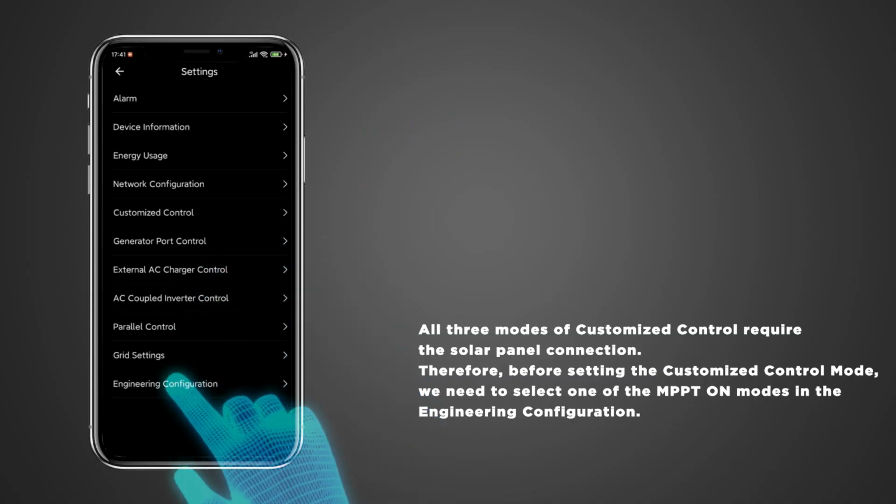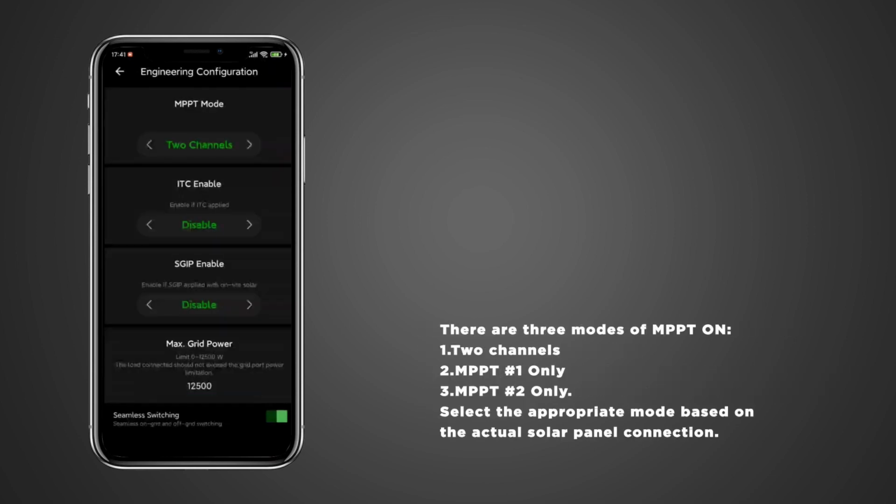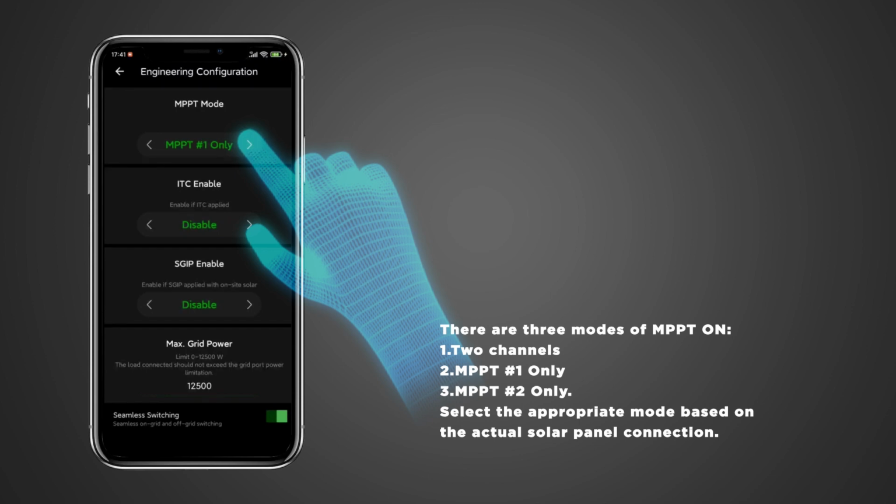All 3 modes of customized control require the solar panel connection. Therefore, before setting the customized control mode, we need to select one of the MPPT on modes in the engineering configuration. There are 3 modes of MPPT on: 2 channels, MPPT number 1 only and MPPT number 2 only. Select the appropriate mode based on the actual solar panel connection.